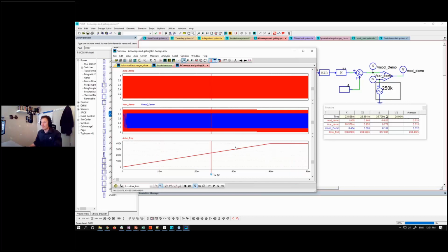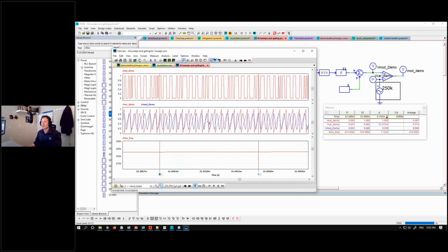If we go even faster, if we zoom in, say right here, we can see that when we have that nice resolution of the duty cycle at the better ratios, we were seeing the frequency in the PWM properly. This is supposed to be 315 kilohertz, but between the narrow pulses and the wide pulses now we're seeing like 200 kilohertz or 100 kilohertz.